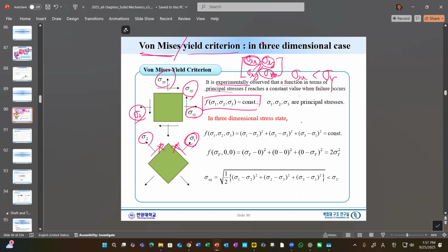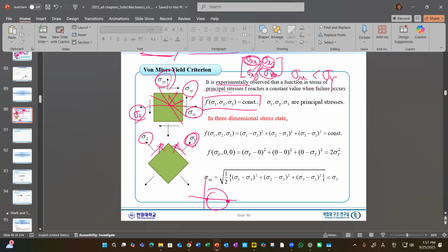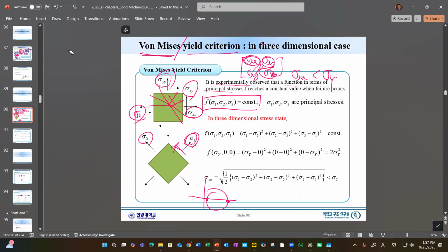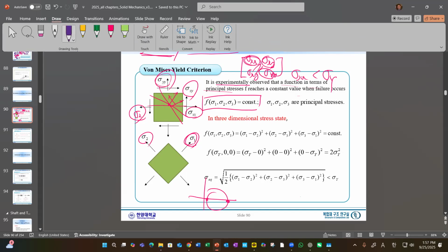You remember, the principal stress is always this one, that, and it means that there is no shear stress. So when we have a given state like this, and we are trying to find what kind of normal stress and shear stress, we can always find the angle or certain direction where no shear stress occurs.